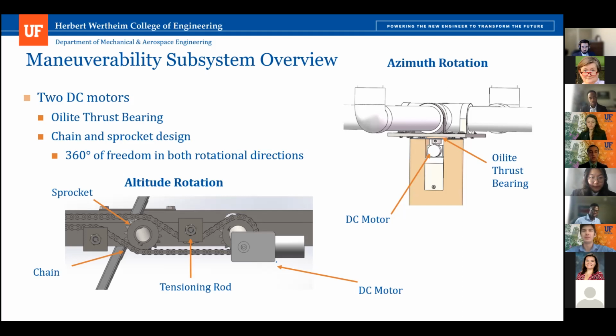I think you'll find that brittle materials tend to be more sensitive to fatigue. Something fibrous like wood alleviates that, because cracks don't tend to have paths to link up going transverse across the grain of the wood. But as a general statement, if something is more brittle, it's going to be more sensitive to fatigue. So keep that in mind.